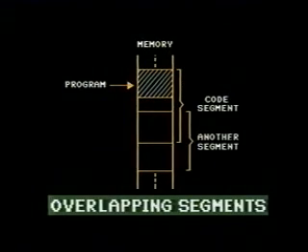Thus, the advantages of using segment registers can be summarized as shown in the graphic. If a program fills only part of a segment, another code, data, or stack segment could overlap the program's segment, thereby utilizing the memory more efficiently.